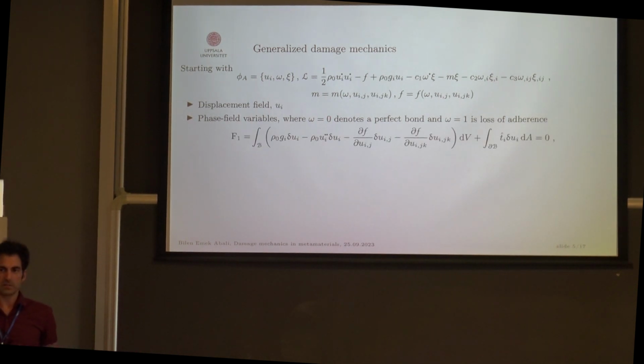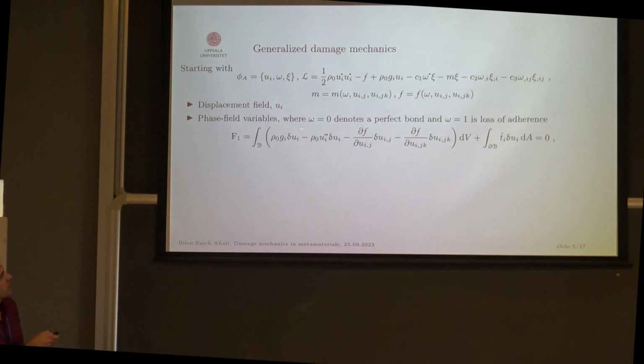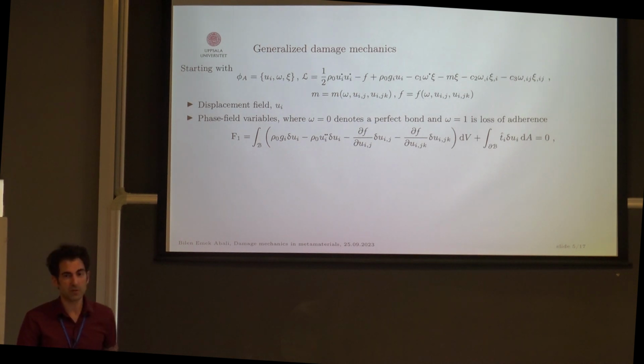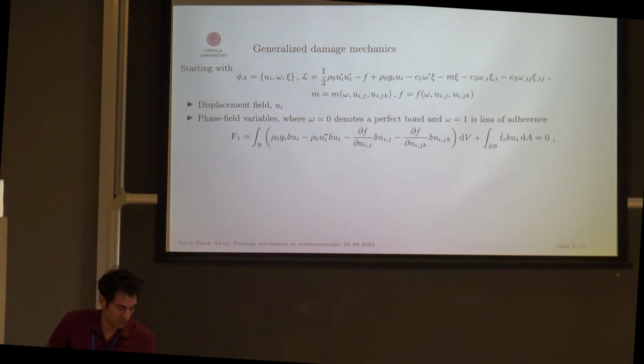So what we have is a weak formulation, and that's all I need. Weak form for the displacement. So that means there is a test function of the displacement. If I solve this, out of that I can get the displacement field. What I need to have is, of course, the free energy here, and there is this so-called Cauchy stress or Piola stress, and here is the couple stress or double stress. And also for the boundary condition, I make my life easy and I just use traction, which is just the force per area.